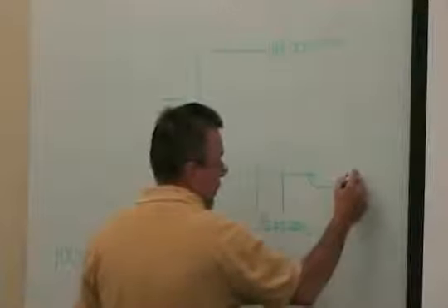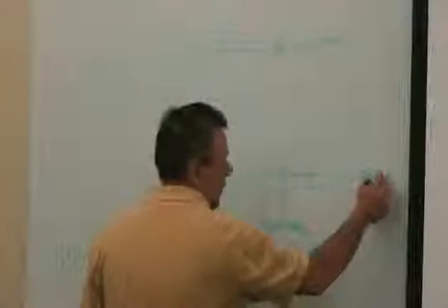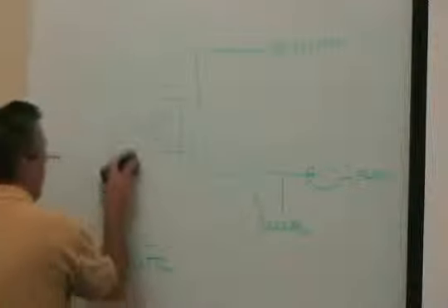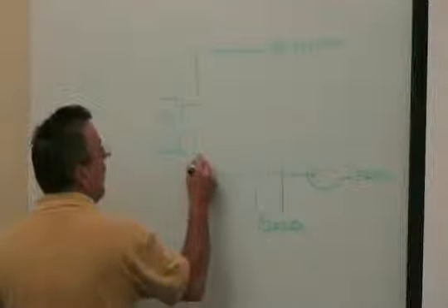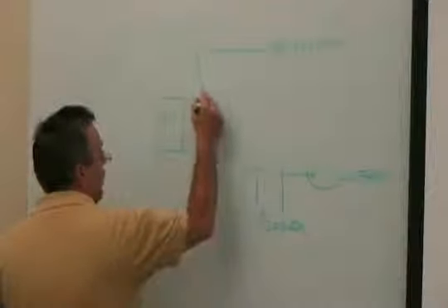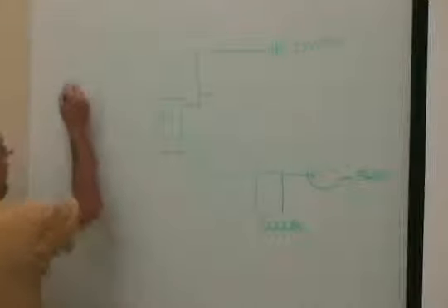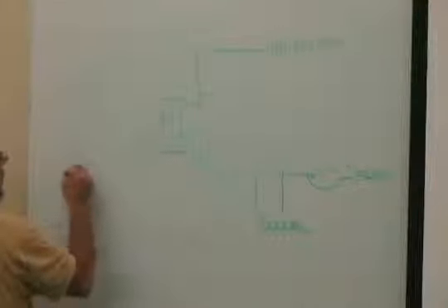This is from the heat pump system. Now I've got a heat exchanger. Well, on the other side of the heat exchanger, I can still have 90-degree water here and 100-degree water here, because I've got a cooling tower, a standard conventional cooling tower.